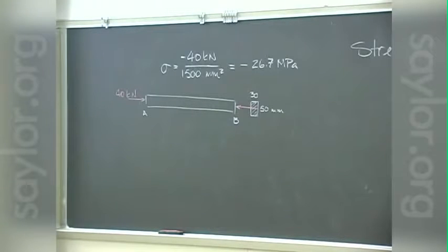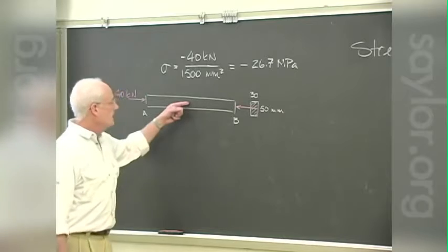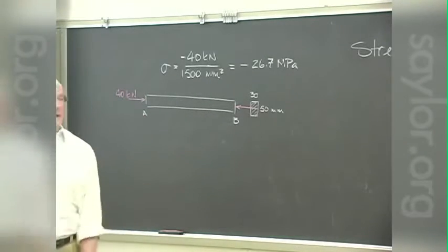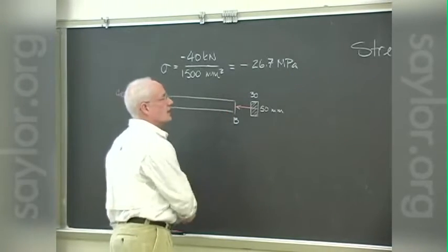One thing we're going to look at later in the term is there's a different type of failure in a piece like that that's under compression, where it can deflect sideways, just like a column would when it's loaded. We're going to have to look at how it resists the tendency to bow out laterally, and in what direction it'll do that.